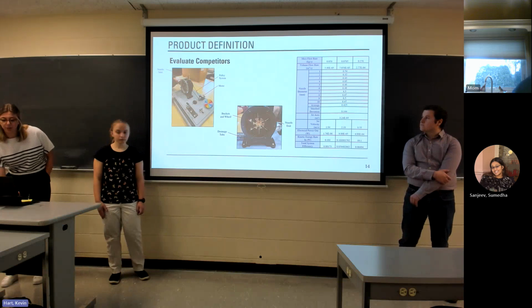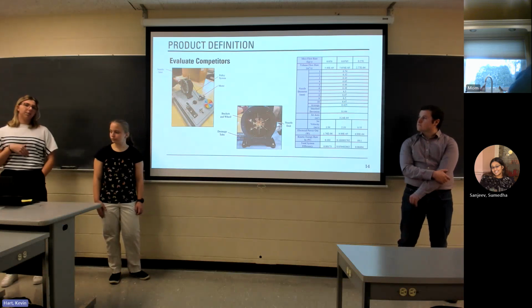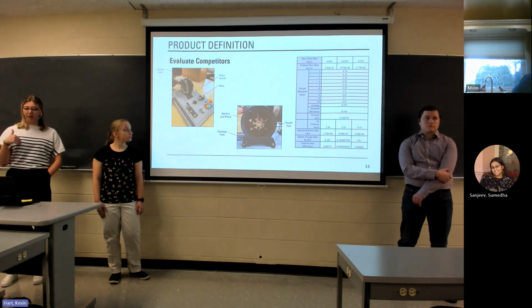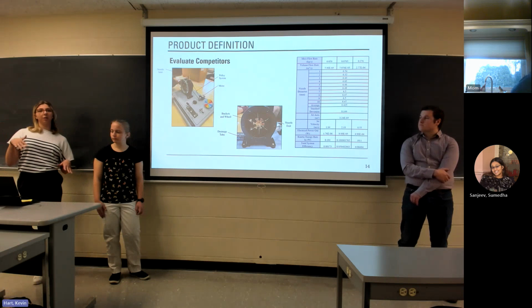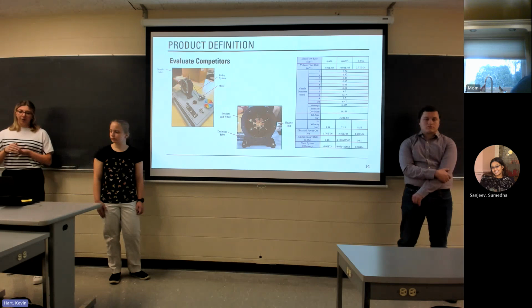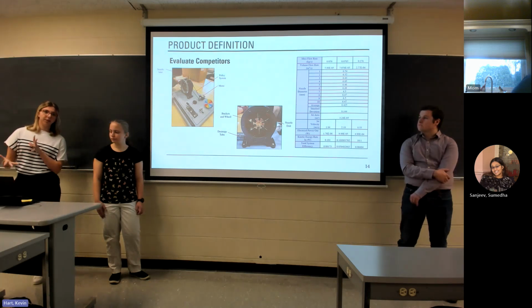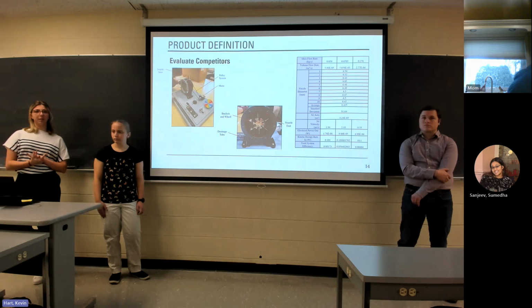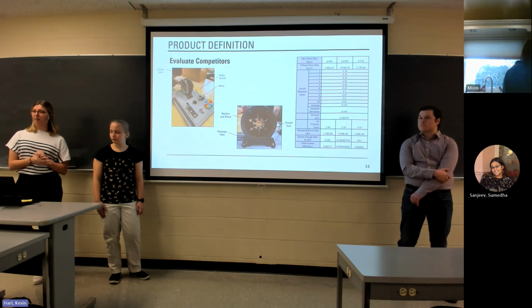Then we did our initial calculations. We hooked it up to a pipe in SGO1, and then we were able to calculate the mass flow rate by timing the water going into a bucket and then finding the mass of the bucket. And then we found the volume flow rate by finding the density of water. And then with the jet nozzle, we calculated the diameter using calipers, and that was able to get us the jet velocity. Current and voltage with the multimeter was able to get us the power, and then we were able to see the kinetic energy and the efficiency.